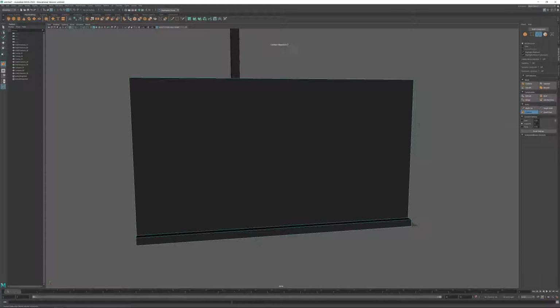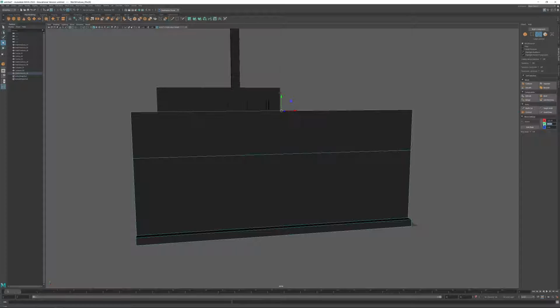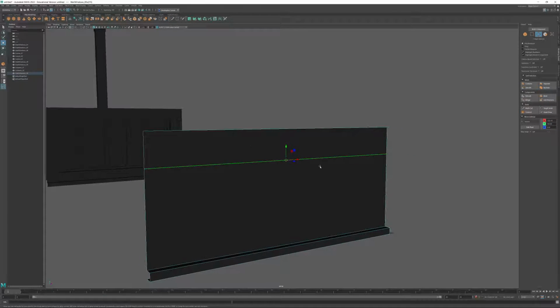Yeah, we can do that. We can connect those. And we'll just turn the segments down to 1 and hit enter. And then let's see, I want the height of this to be 200. And we'll take this one and we'll set it to 150, giving me a 0.5 meter lip along the top.